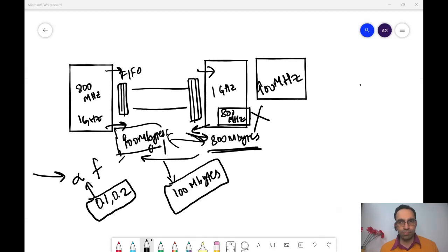To overcome that latency between these two voltage islands, we use shift registers. Latency means that I'm operating at 1 gigahertz, but to transfer data from one part of the chip to the other, I take 200 picoseconds. So when the clock edge comes on that side, my data is not yet ready there. So I need very small temporary storage, just 1 word or 2 words, and for that I use a shift register to match up to that speed.